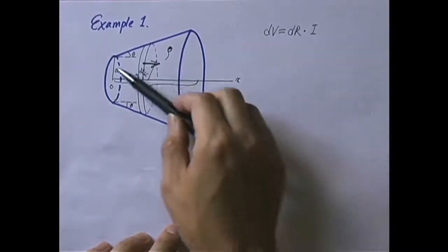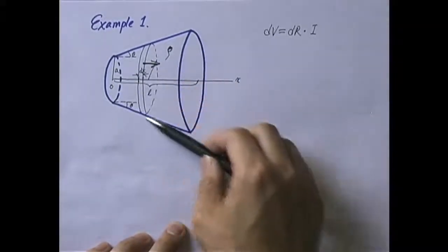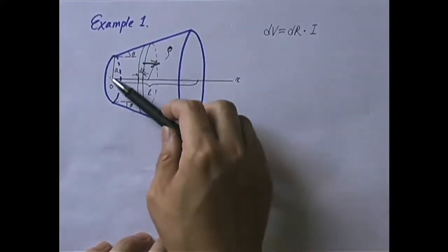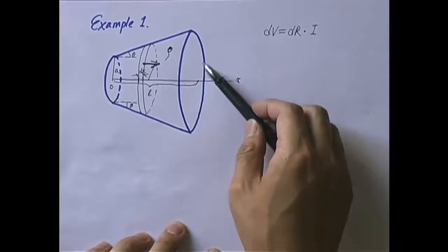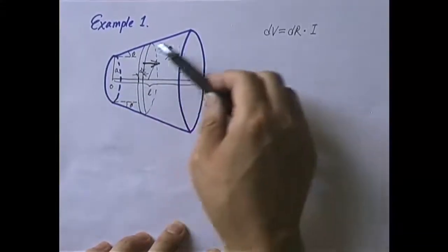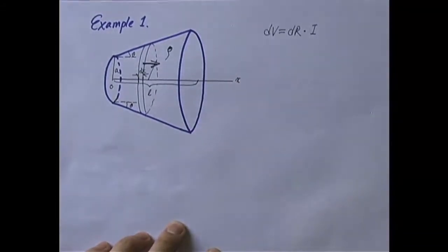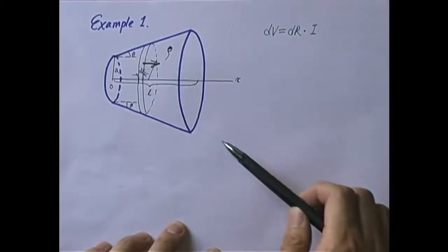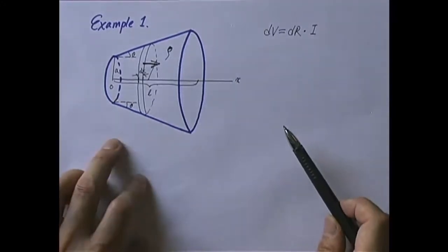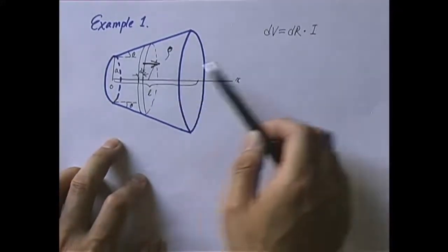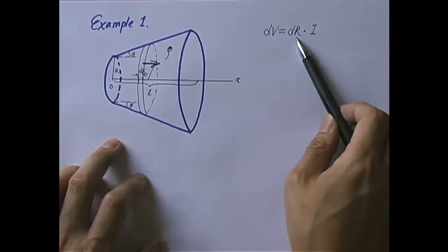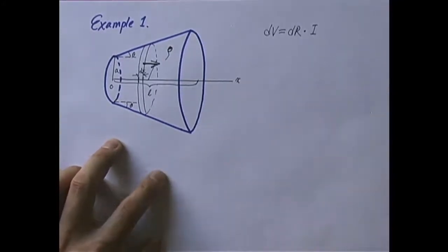Then due to the conservation of charge, there would be an accumulation of charge, building up a positive charge, and we know that doesn't happen in a real circuit. Charges can only flow from place to place. They do not get accumulated or depleted, and therefore every one of these layers has the same exact current. They don't have the same R value, but they have the same current value.